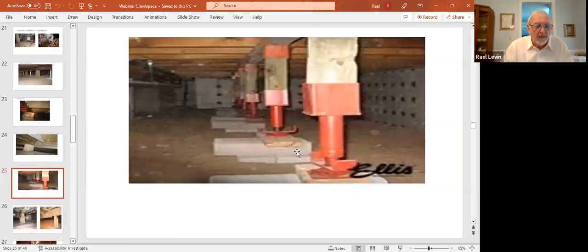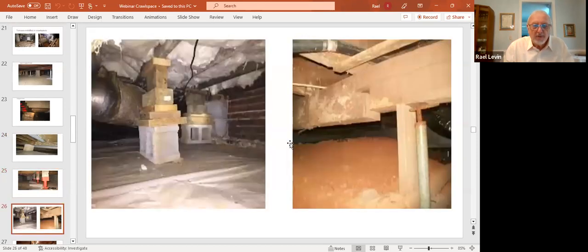You see here several temporary supports sitting on what we call a cap block. Just a cement block there. That's insufficient support for the floor system as you see it. And there are all kinds of different ways that people would come in and put stacked up wood, and even this masonry block that's here is installed incorrectly. It should have been 90 degrees over so that the holes that you see there were vertical instead of horizontal to give it some more support. So you can see support here, support there, it's all temporary stuff.